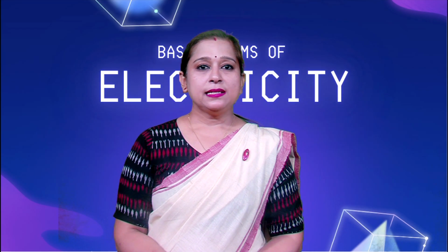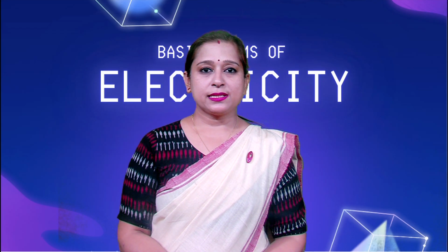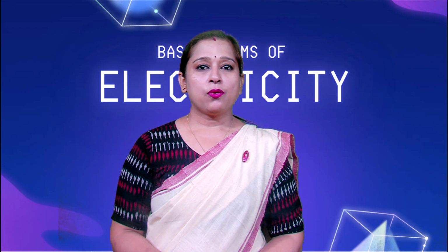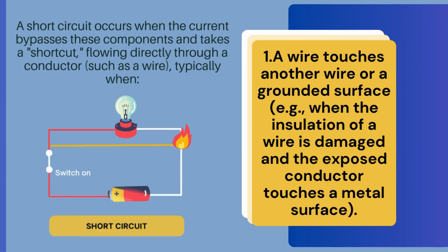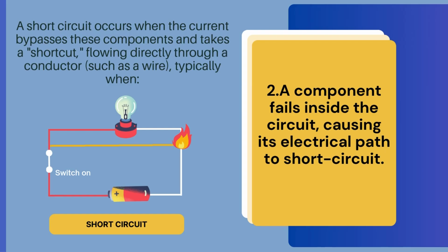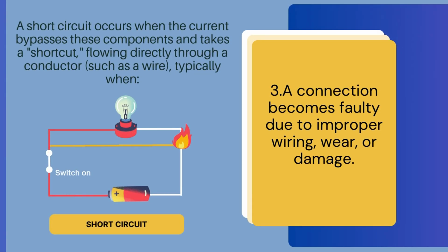In a normal circuit, electrical current flows through components like resistors, bulbs, or appliances which offer a certain amount of resistance. However, a short circuit occurs when the current bypasses these components and takes a shortcut, flowing directly through a conductor, typically when a wire touches another wire or a grounded surface, a component fails inside the circuit causing its electrical path to short circuit, or a connection becomes faulty due to improper wiring, wear or damage.